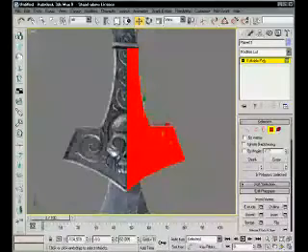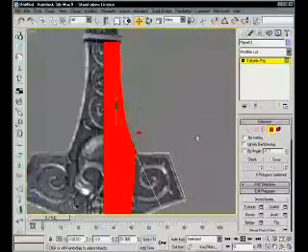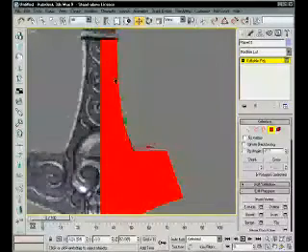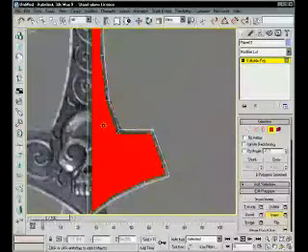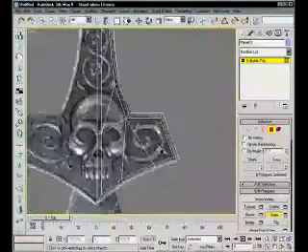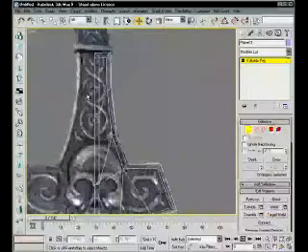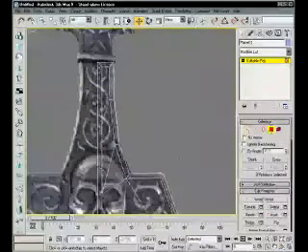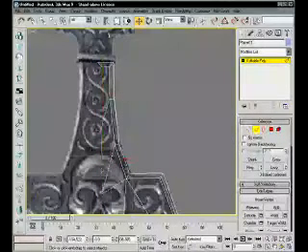Remember that as it's low poly, we don't want to model in every detail, but I'm just going to model in these edges around. Now, by using the inset tool, press that, and pull that in. And as you can see, it's insetted that thing. It's very self-explanatory, really. I don't need that poly. It's always good to delete polys as you go, where you don't need them.